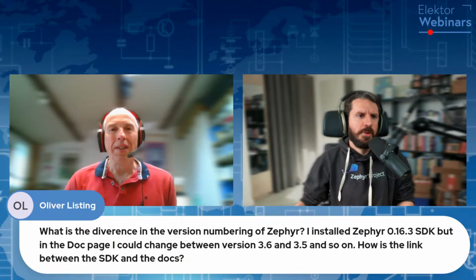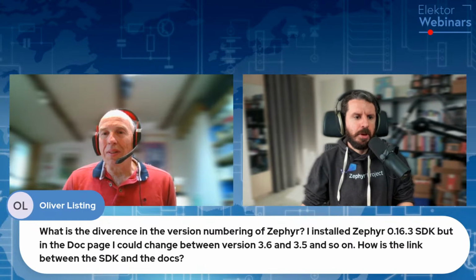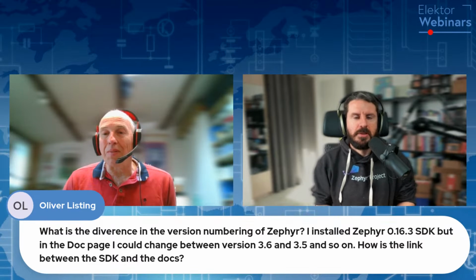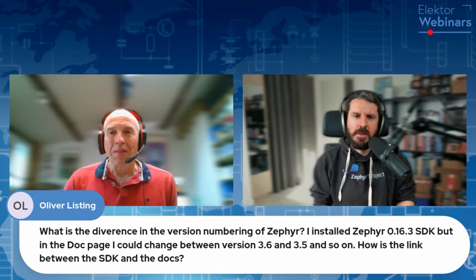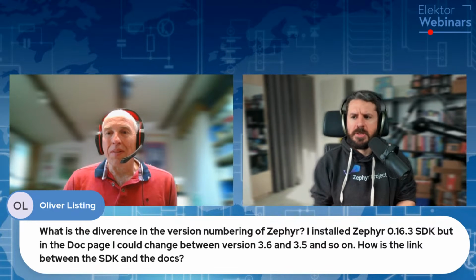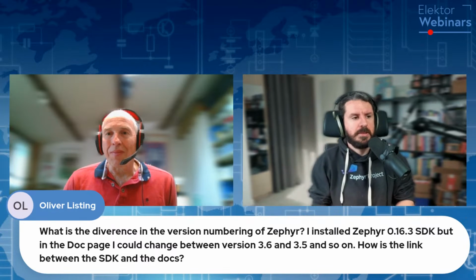But there were some questions regarding footprint, right? Like, how little RAM, how low can it get on ARM? Think Cortex-M0, basically. So 2K of RAM, I think, is really the bare minimum, and probably something like 8K of flash off the top of my head. It's going to give you a really small app, but yeah, Cortex-M0, to give a ballpark figure.